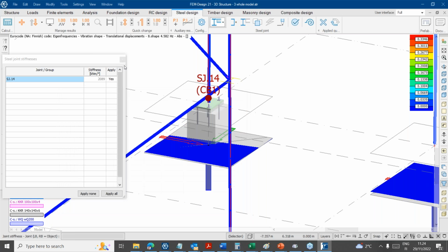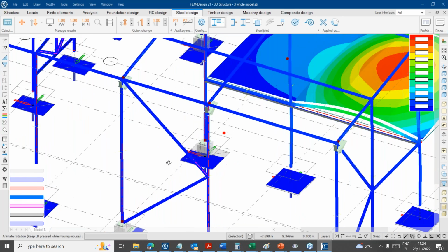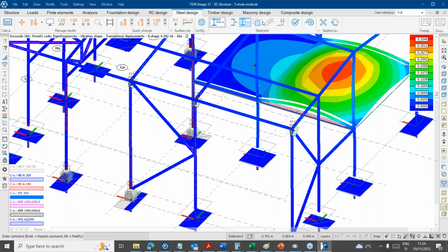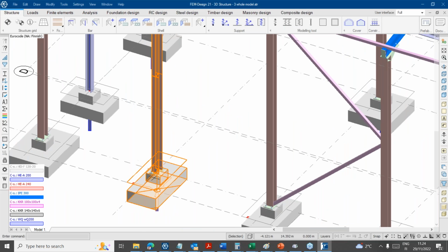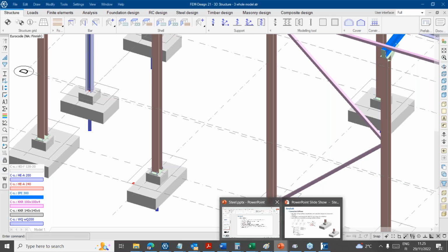But anyway, it's good to understand when we are calculating the total stability of the building, we have to design our connections really stiff, make certain that they are stiffer than the column or classified as a rigid connection, or if they are not, then we have to take those connection stiffnesses into account. And in our software, it's easy. If you have a connection design, you just use this stiffness button to calculate the exact stiffness. And always the good option is to make connections which will be classified as rigid or classified as pinned. That's a really neat way to handle your frames and design of frames.